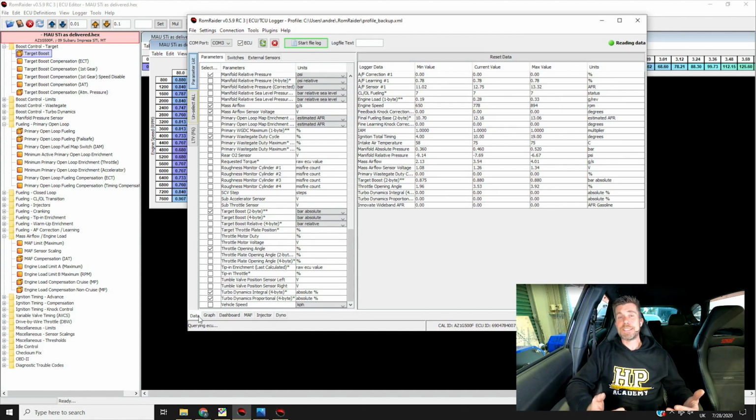So what this results in is a lot of heat soak in the engine bay, and we need to get rid of that heat soak and get back to realistic operating conditions before we start logging data again. So once we get back up and running, we want to drive the car for maybe 2 or 3 minutes at speed on the open road, on the racetrack, just get airflow through to get rid of that heat soak condition. So that's one thing.